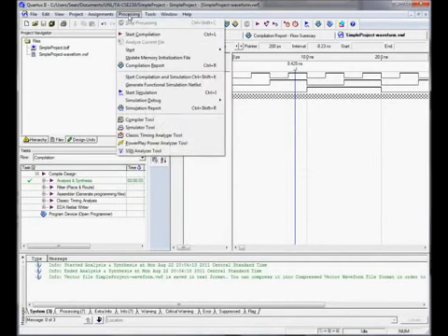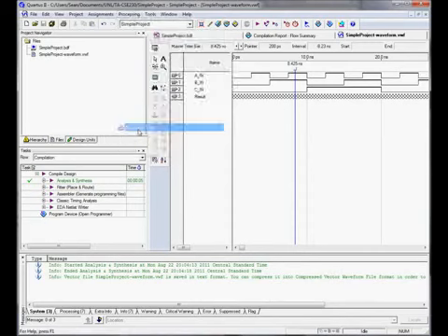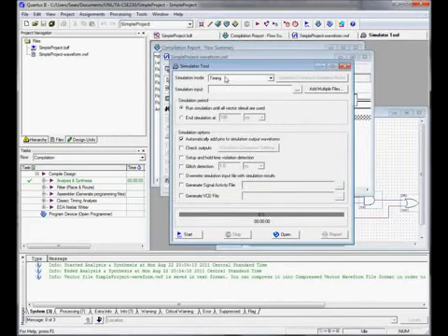So we're going to go to processing and start simulation, or you can go to simulator tool. I prefer the simulator tool. There's two different modes of simulation. One is timing and one is functional. Functional just simulates the exact results. So if I have A and B together, it will give you a C, or however we define our function.